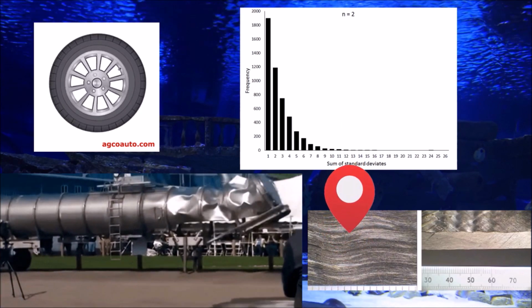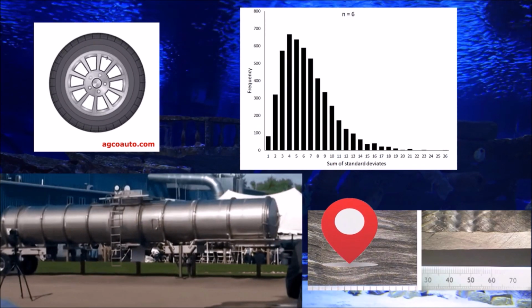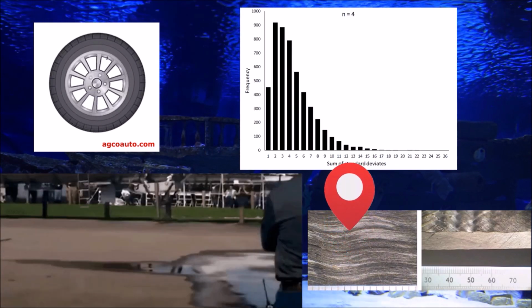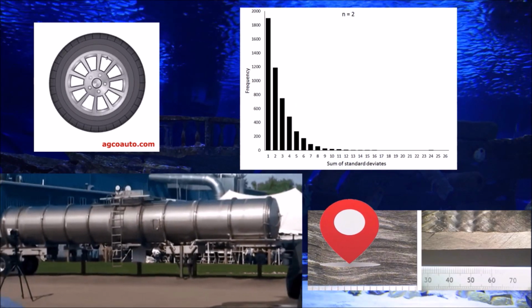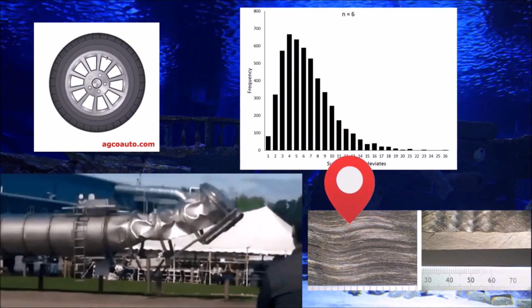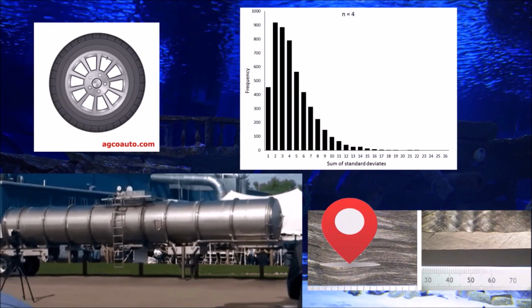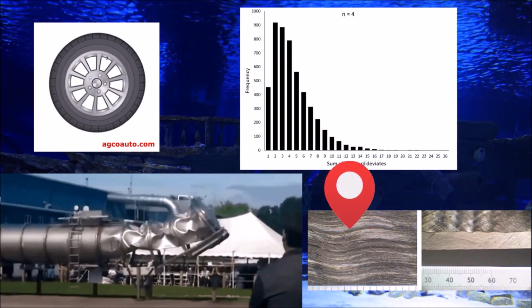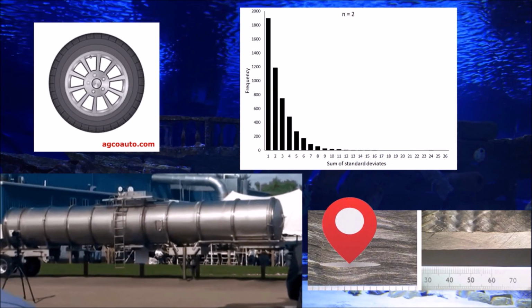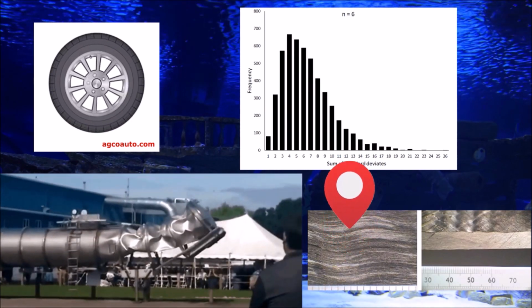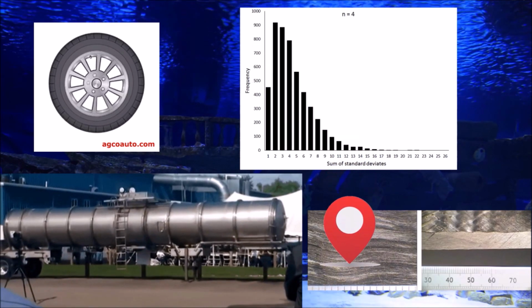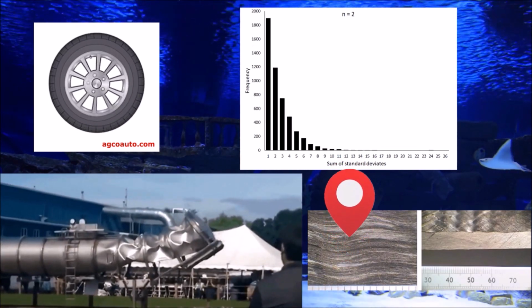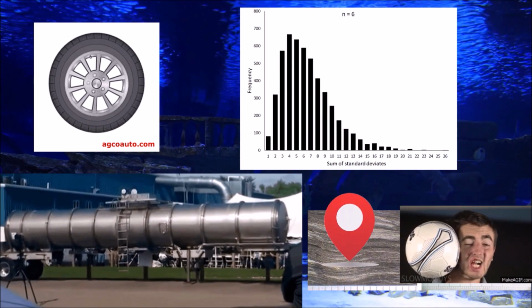This is also reported. And also changing the composite type from carbon epoxy to glass epoxy changes the properties and the defects associated with that. In general, the presence of defects has a significant influence on implosion resistance, and this definitely informs the design, manufacturing, and materials choice to enhance the safety and reliability of composite cylinders.